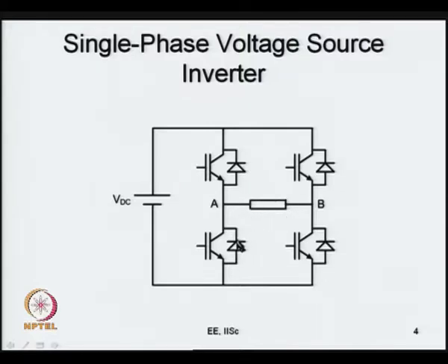So, this plus VDC and minus VDC can be applied across the load for varying durations, and that is bipolar PWM, because in the VAB output, in the positive half cycle as well as in the negative half cycle of the fundamental voltage, you see positive pulses as well as negative pulses. That is what we saw in the last class. So, that is the bipolar PWM, and we would use the more popular unipolar PWM.